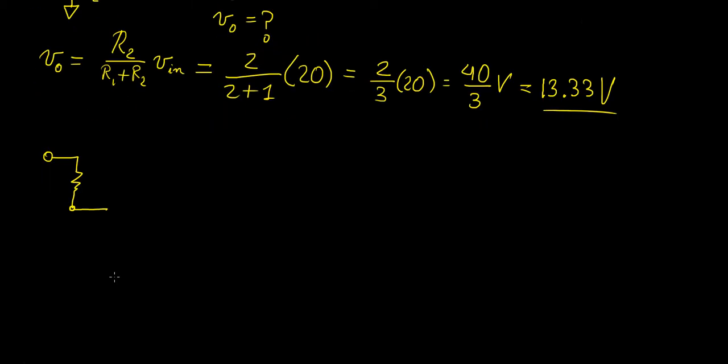So far we have considered the cases in which we only have two resistors and the ground. But let's see what happens when we have R1, R2, and now we attach another resistor, or a load, which we're going to call RL, which is also connected to ground over here. Can we actually calculate the potential drop across this resistor? We could implement the same thing again. We could just have a current coming in over here.